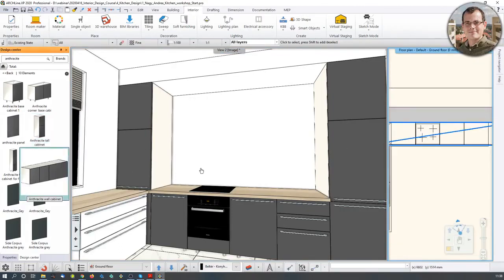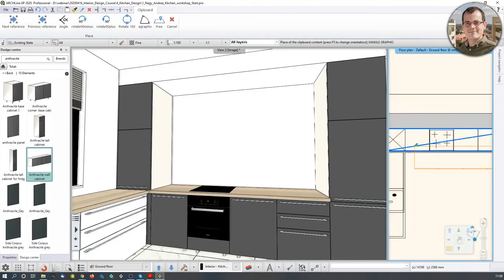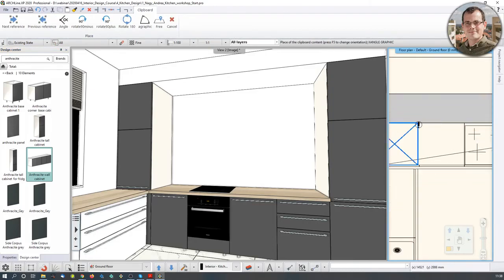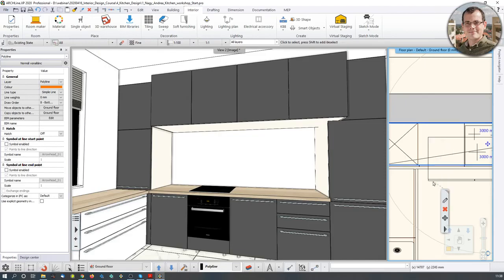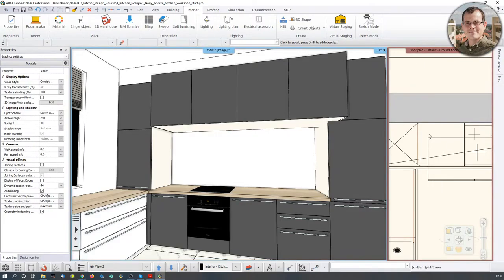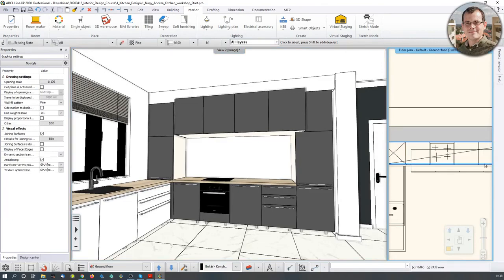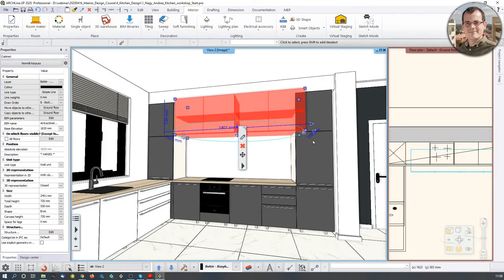So let me just drag, drop it, and drop it on them like that. Okay, if this happens, this is usually because the software is trying to do something with this cabinet, maybe override an element which you already have. So if you can't snap it to a corner, let's just position it wherever you want, click on it again, and then you can just move it there. If the drawing is getting pretty dense and you can't find where to click for this cabinet, then go to the 3D, select the element, and that would select the element in the 2D as well.